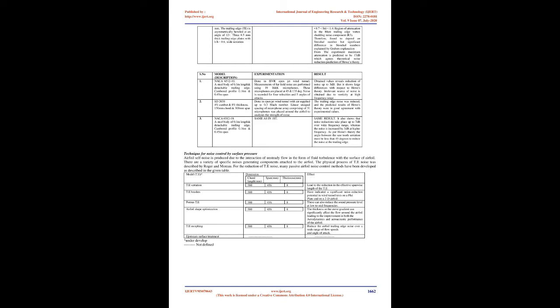An optimal choice of flow resistivity for a Poroserrated configuration has been identified where it can surpass the conventional serrated trailing edge of the same geometry by achieving a further 1.5 dB reduction in the broadband noise while completely suppressing the vortex shedding tone. A weakened turbulent boundary layer noise scattering at the Poroserrated trailing edge is reflected by the lower turbulence intensity at the near wake center line across the whole span-wise wavelength of the sawtooth.